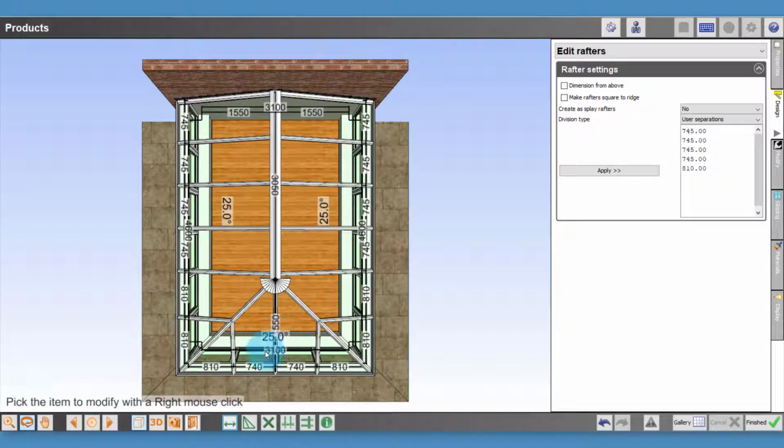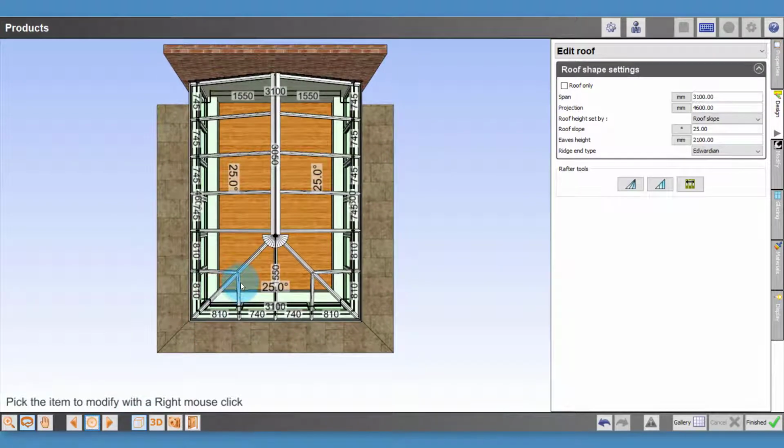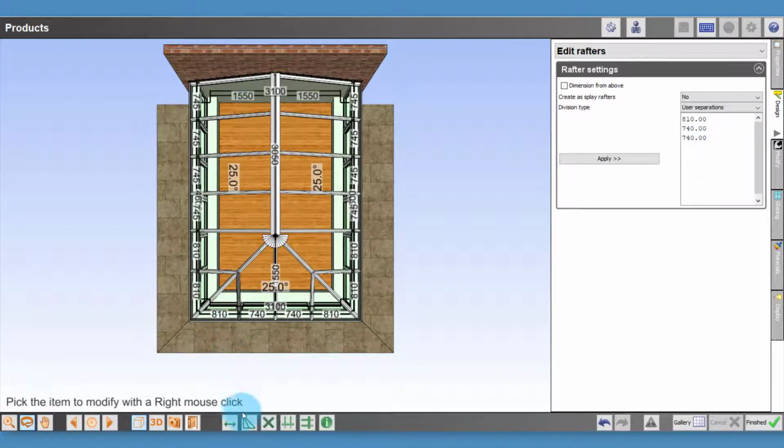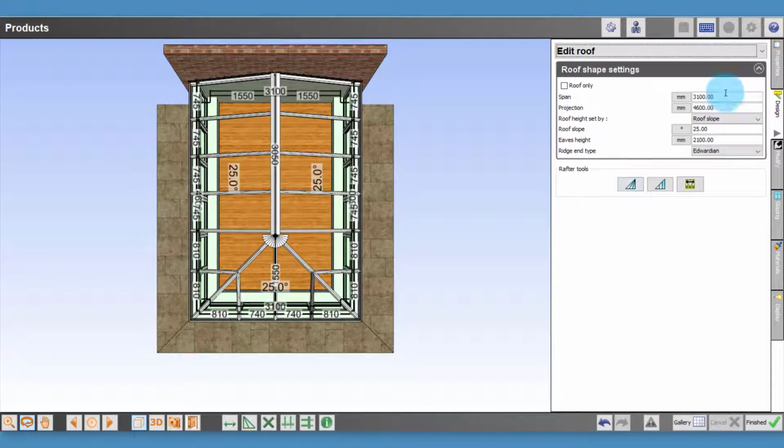Finally, there's a splay option. So if you've got a rafter in the front, you can splay it and jack it independently using the icon provided. This can also be done in the edit area using the drop-down menu. You will notice that these icons will perform this function on the entire layout as opposed to the rafters individually.